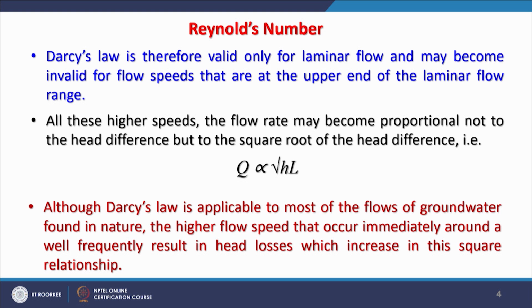So, what is that head loss? It is the drawdown, which we will be discussing in later videos, but anyway here I can introduce it in a very brief manner. The head loss is a cone, and the apex of the cone is at the water level within the well. If this cone becomes very sharp, then the head loss is very high. If this cone remains very shallow, then the head loss is less.